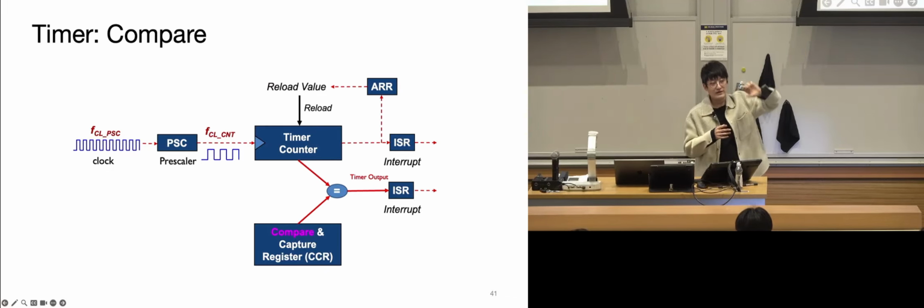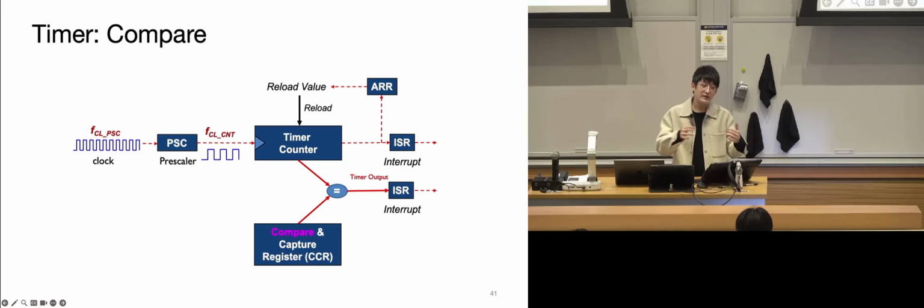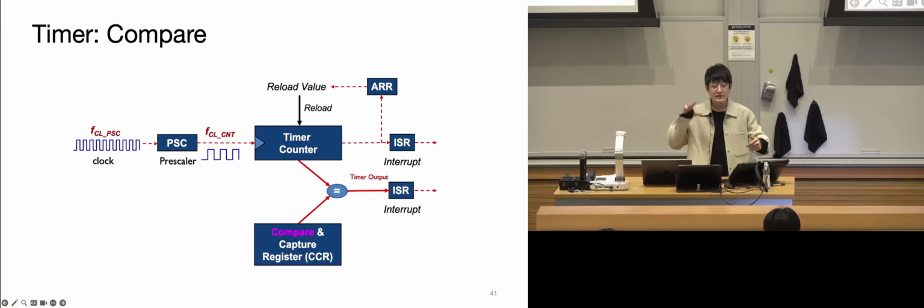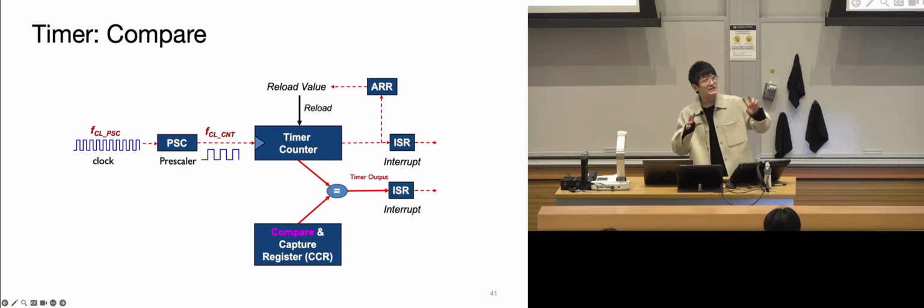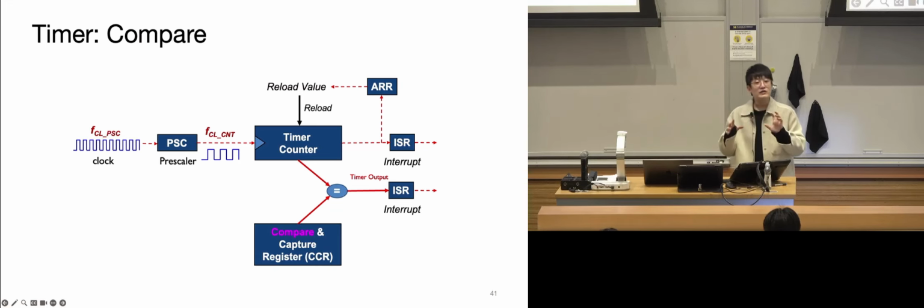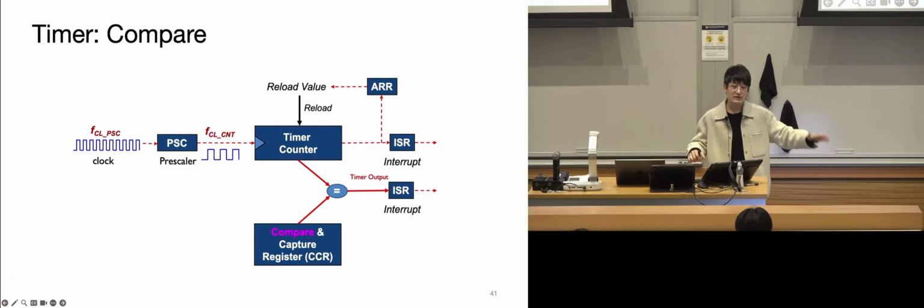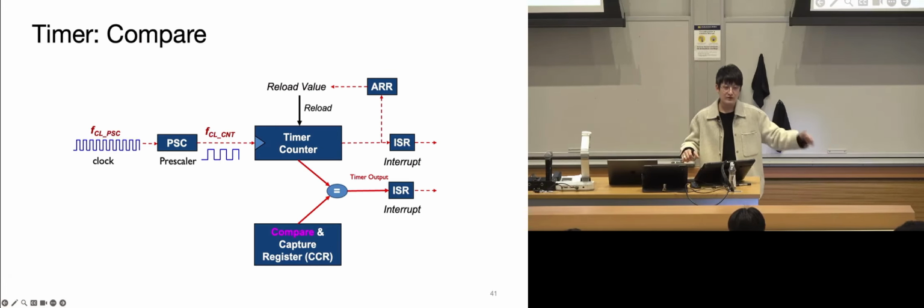But once the clock is set up with the ARRs and counters, the counter counts on its own. It doesn't take the CPU or core's attention to do that, because it's a separate piece of hardware. It's implemented on hardware, so it doesn't occupy the computation power from the core. It's running on its own clock and its own registers.